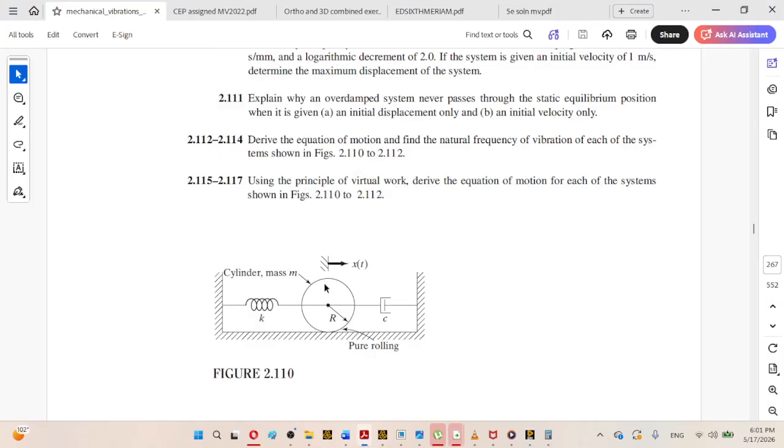The planar joint was applied such that this sphere is in planar motion, for example it will be rotating, and its center will be translating in the x direction. So actually only the planar joint worked. I have tried a lot and consumed much time on investigation. So you will be applying a planar joint. No other joint actually worked and brought the nearest results.